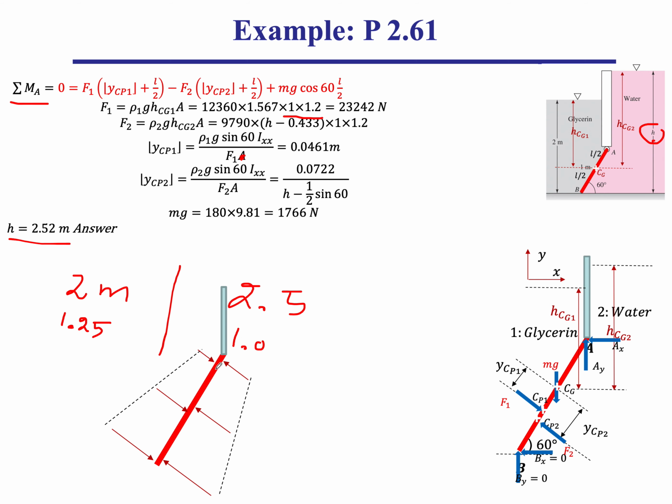appreciate that there is a pressure distribution on the glycerin side, and remember dP/dz is minus rho g. That's the only equation we're working with in this chapter, minus rho g. So the slope at which the pressure varies with depth of submersion Z depends on ρg.